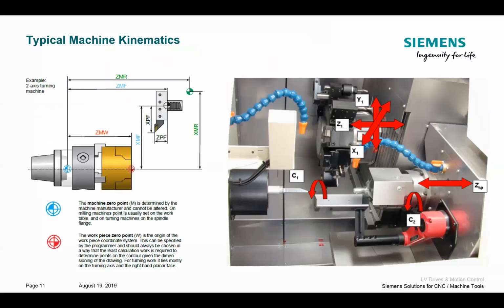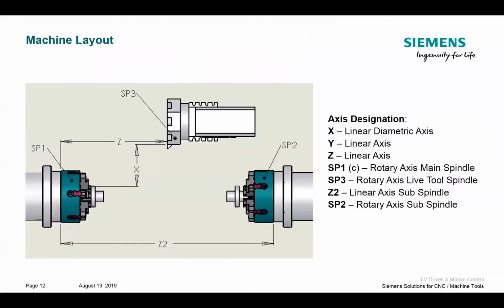precedence from that point. So this way, it makes it really easy for handshaking between all these other linear axes that are moving around for us. So machine datum is going to be the front center of your spindle. Then from there, we're going to take a look to see what's driving from there. So my Z2 is going to drive that sub-spindle, as I see here to the right. X and Z, they're going to handle moving my turret out of the way. And then my spindle 1, spindle 2, that's just going to handle my main spindle, sub-spindle, physical chucks when I start inducing a rotation there.